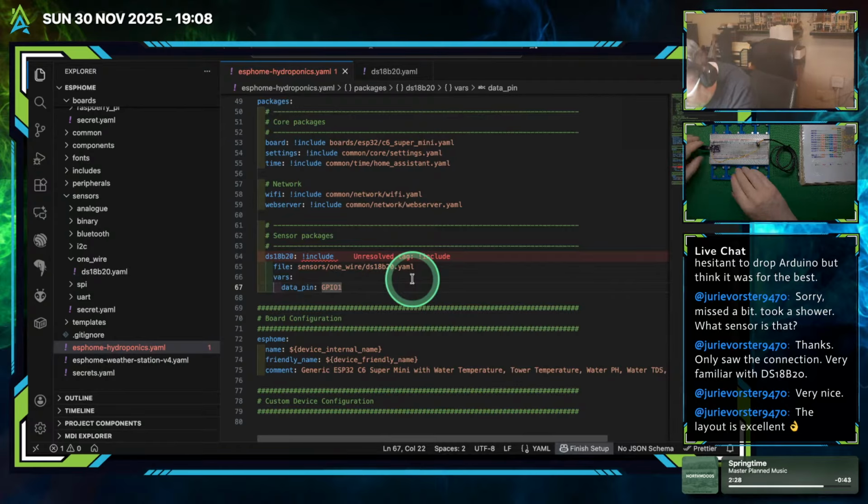So in the meantime, what's your next project? Yes, Yuri, the power rails. Well spotted. Yours truly is using two different boards, and this one has a break here. So you could put 5 volts here and 3.3 volts here, for example, or have 2 different MCUs on the same board. And I do that quite often, and I go, but why isn't it working?